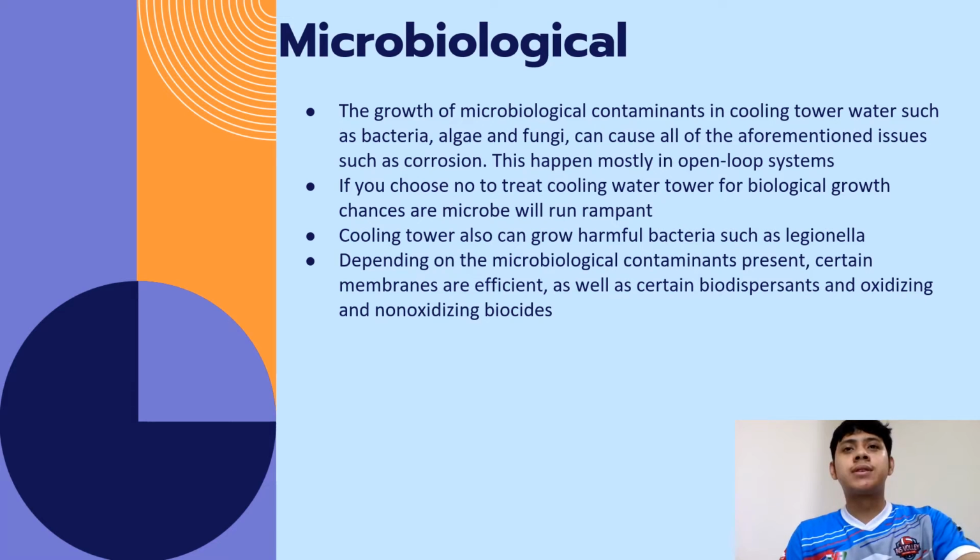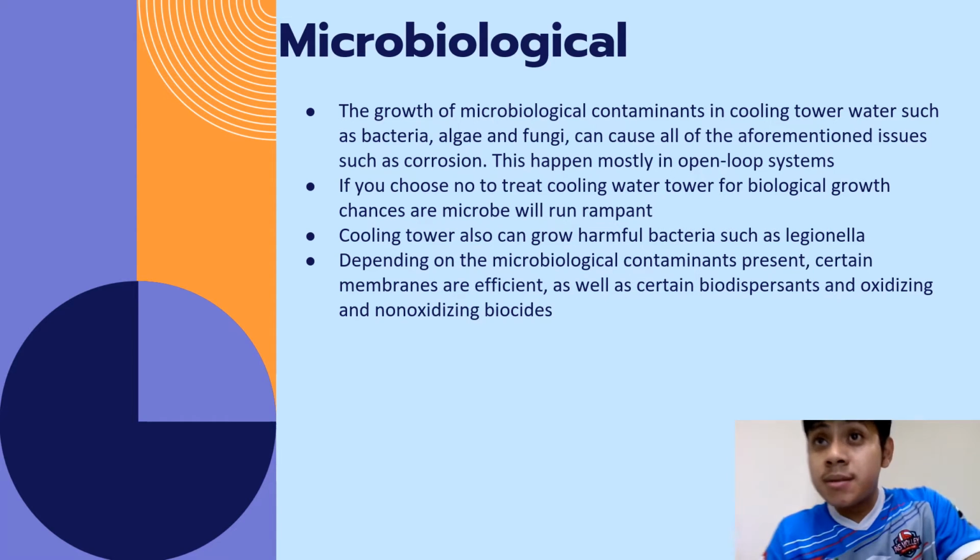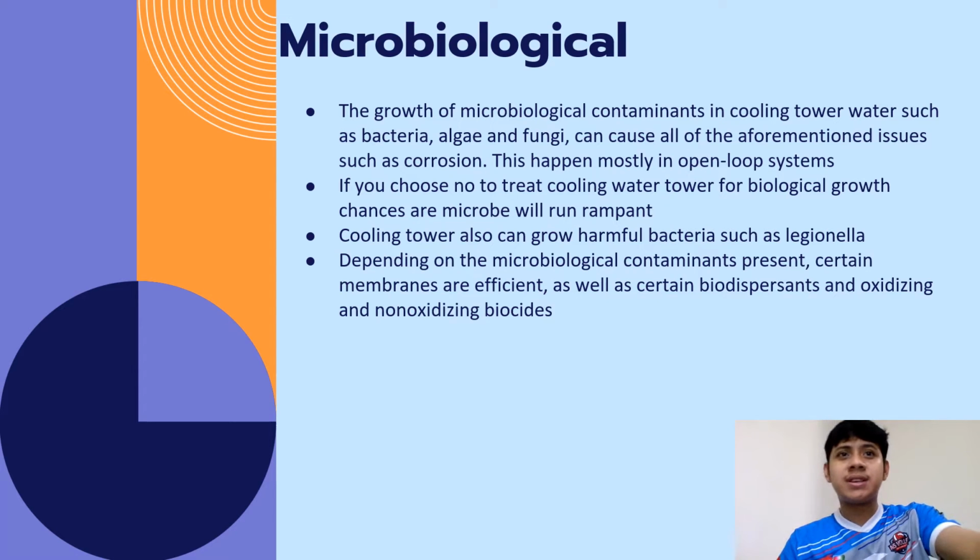Cooling tower also can grow harmful bacteria such as Legionella. Then, depending on the microbiological contaminant present, certain membranes are efficient as well as certain biodispersant and oxidizing and non-oxidizing biocide.